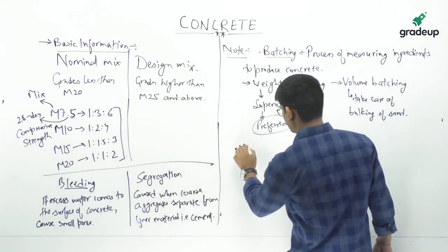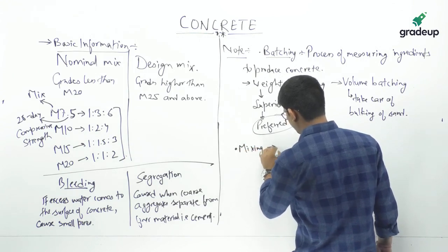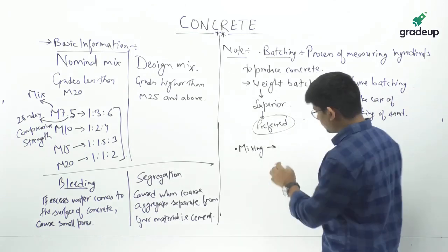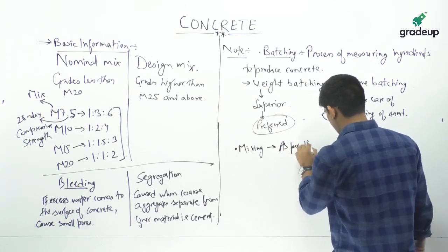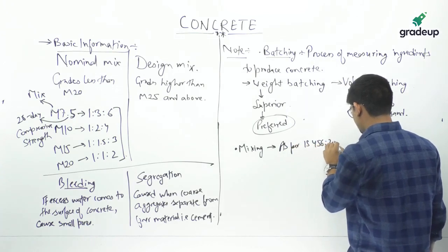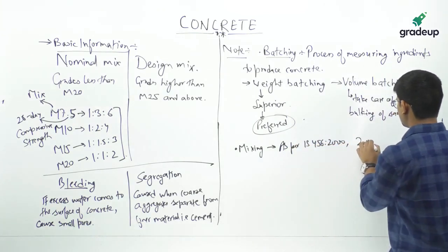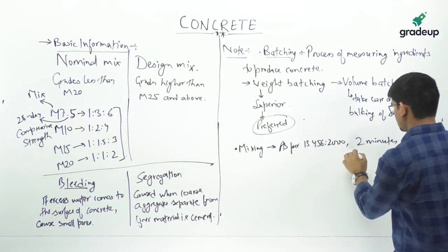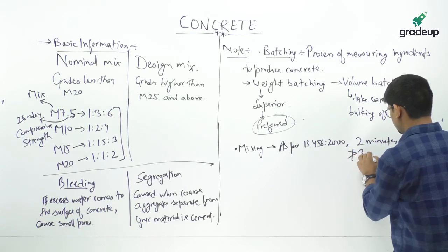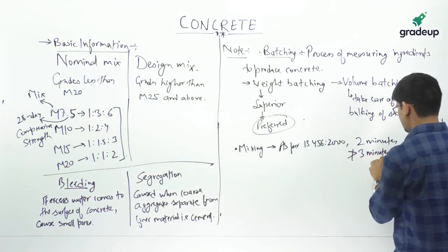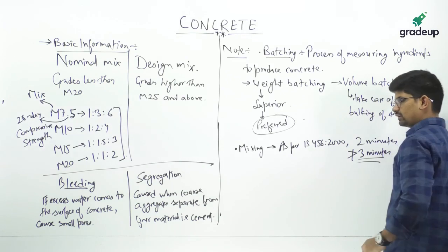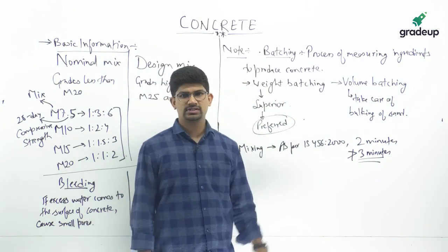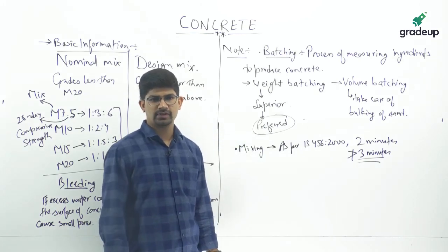Then there is one point regarding the mixing time. As per IS 456:2000, the mixing time is 2 minutes. It should be about 2 minutes, but not greater than 3 minutes. This is the highest mixing time which can be done. So during mixing, 2 minutes is the recommended time as per IS 456:2000.